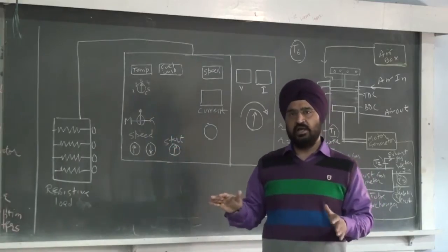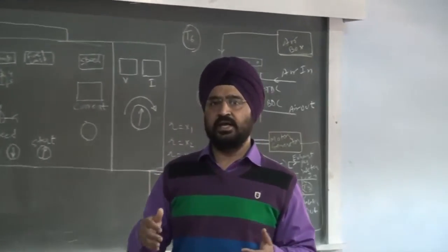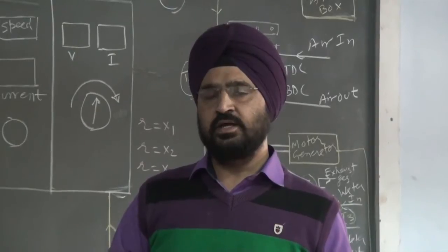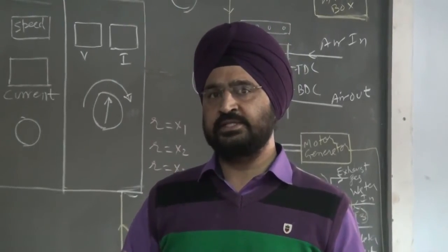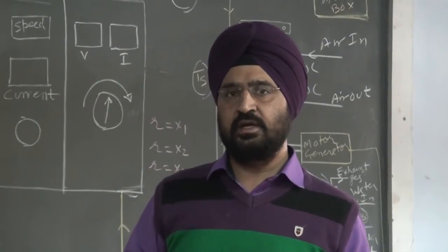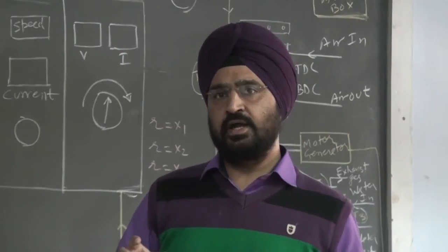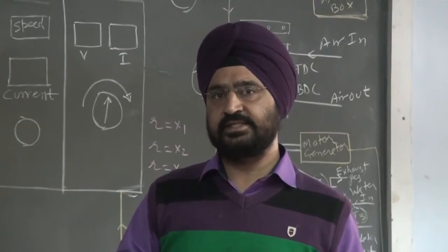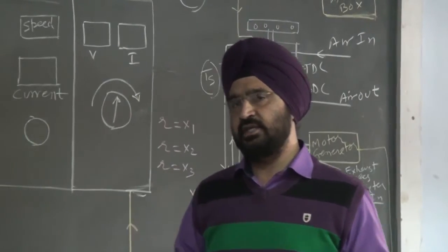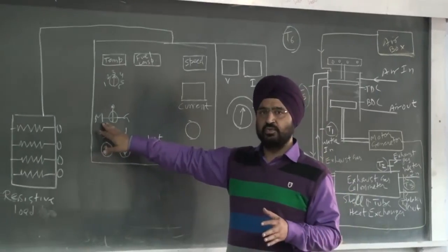First of all we will run the engine on generator mode, and then again we will run the engine on motor mode. So the 2 things are there. Generator mode means the supply of the fuel to the engine will be there, and loads and all the things are there. We will apply the load and note down all of the currents and various other readings. That will be the generator mode, and then the other thing will be the reverse mode, the motoring.